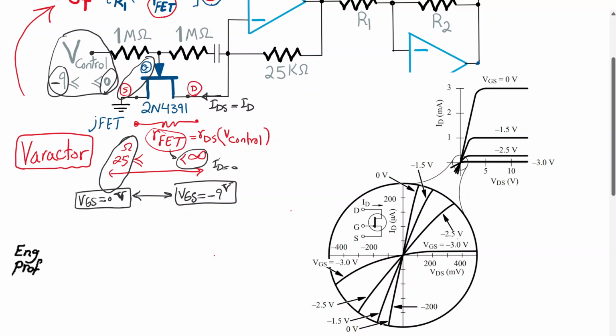So in the JFET, this is the IDS as a function of VDS: the current of the JFET is on the y-axis, and the VDS, the voltage between drain and source, is shown on the x-axis. We don't want to deal with the saturation region. That's not what we want. We want to deal with the deep linear region here, the red circle that I'm highlighting.